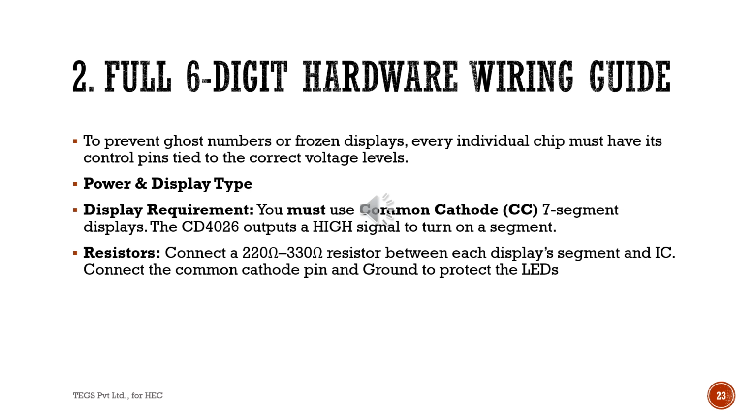To prevent ghost numbers or a frozen display, every individual chip must have its own control pin tied to the correct voltage level. Power and display type. Display requirement: you must use a common cathode 7-segment display. The CD4026 outputs a high signal to turn the segment on.